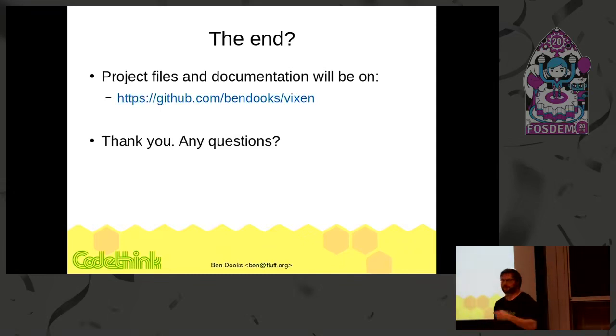Now, one VIC-20 was probably one more than I needed. I've actually repaired the second one as well, because I could probably sell that back on. It turned out the VIC chip on it had died, so that was why I wasn't getting anything out of it. That was another evening of wondering why on earth it was not working, with a sidetrack of probing through, finding out what was wrong, and the fact that China still sells VIC-20 chips.